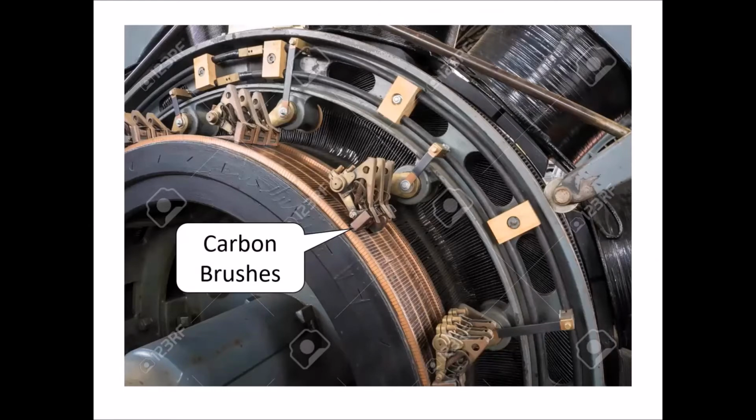Let's have a look at a carbon brush. Oh, just before I do that, it has to be admitted that inside the rotor of this so-called DC machine, steady current, all the coils actually are carrying AC current. But that commutator, that thing at the end there, copper segments on a cylindrical former, is in fact a mechanical rectifier. And it rectifies the AC and produces lovely smooth DC for the outside world. But it's frequently not realized that all machines actually are AC, but from the outside world point of view, the current that is fed in and the voltages are DC.